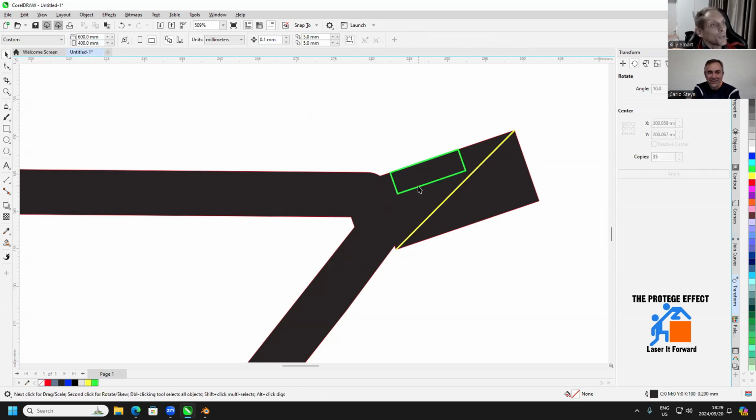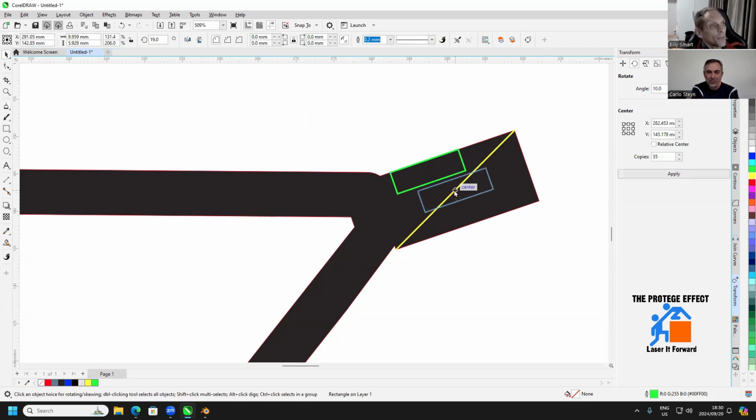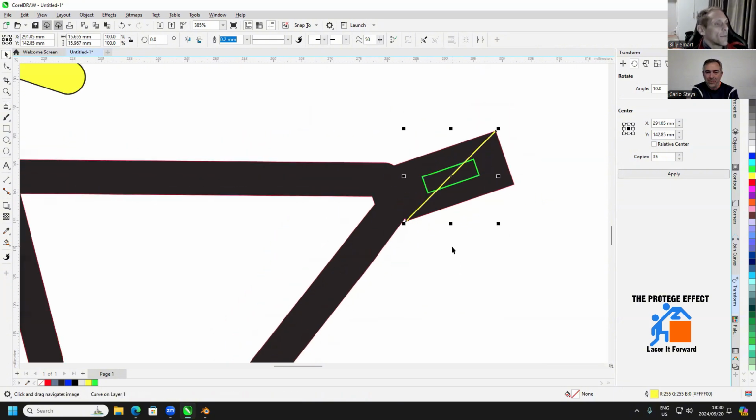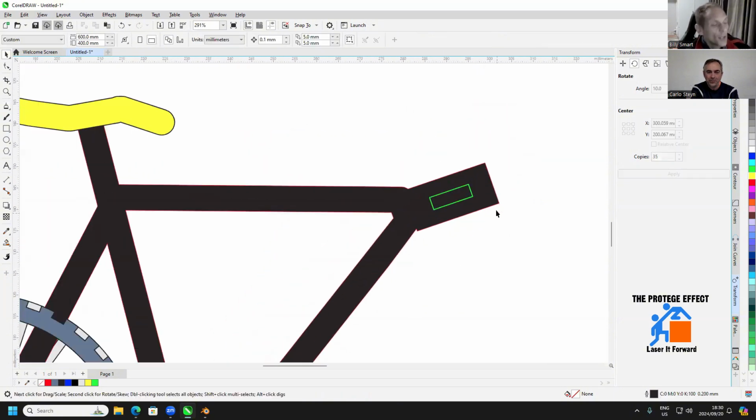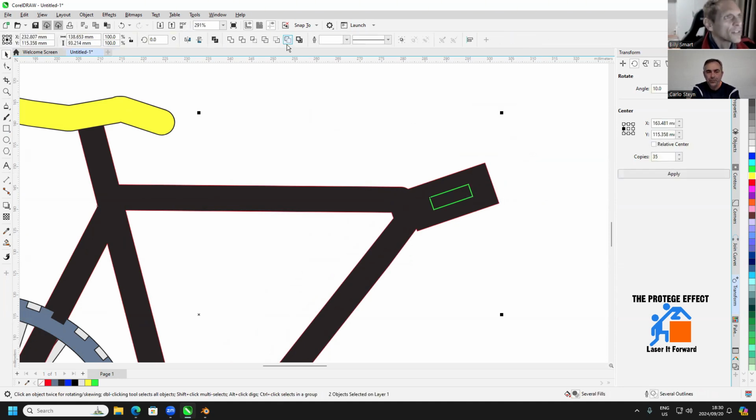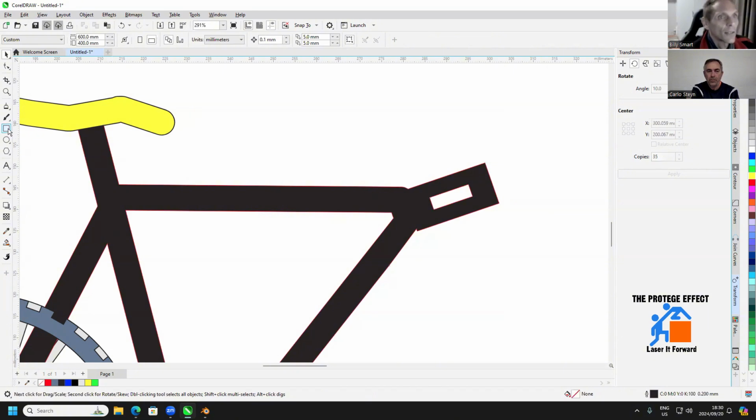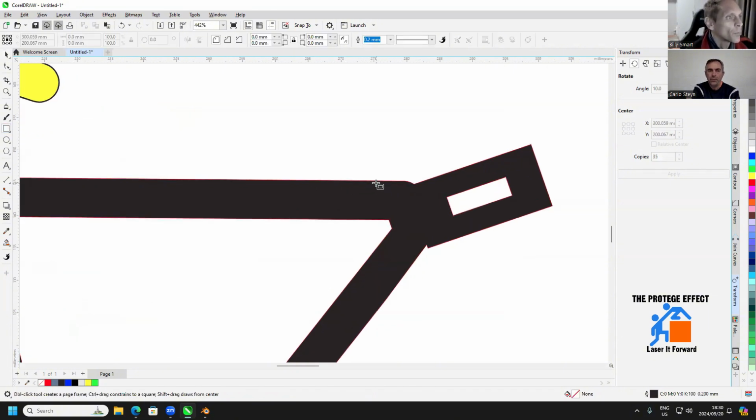There's certain numbers with certain material, with every different material that's out there, as a matter of interest. And on the MSDS or the manufacturing settings, they'll actually tell you never make any part or any hole smaller than 1.5 times the thickness of your material. A lot of factories and industry have certain standards, and it's actually based on the strength of the materials, what the material is made of, and what it can handle. It's not actually about your machine. It's about the material and what they call design criteria.